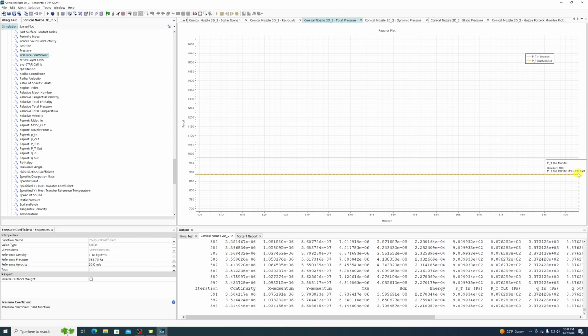Right? The flow is generating forces through viscosity, dissipating energy into the walls kinematically. Not thermally, but kinematically. And we're losing some energy in the flow. So we get a drop in total pressure through this thing.